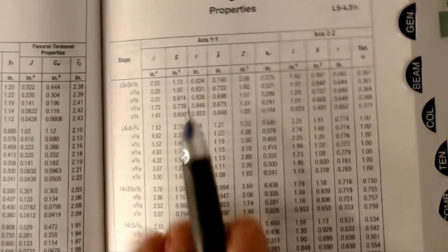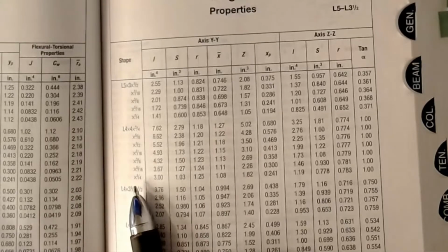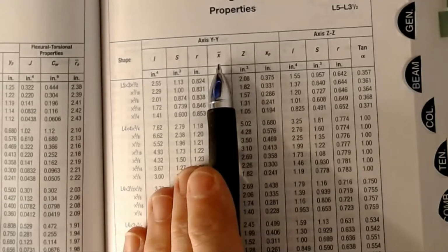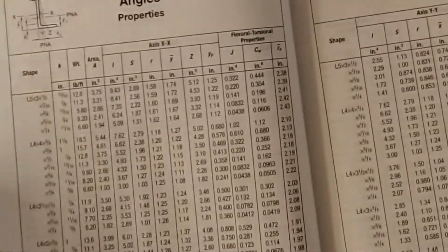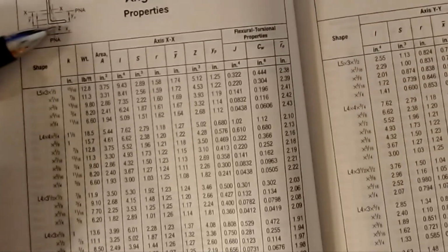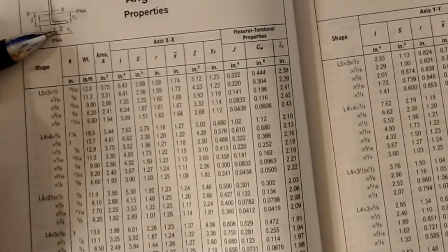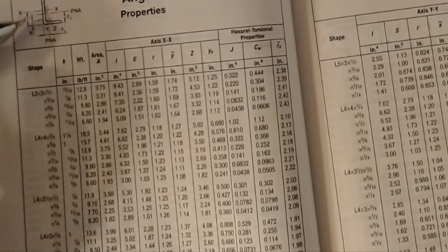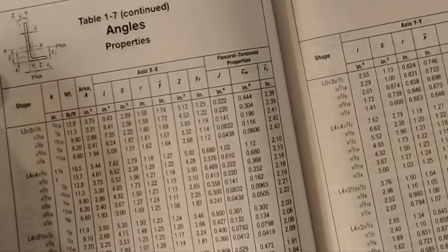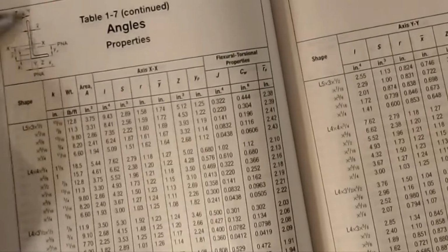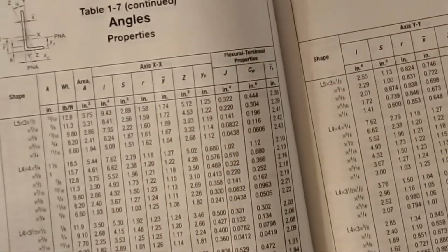Okay, now if we slide over, now we get into a y-axis calculation. And so 4 by 4 by quarter, and we come across and we have the exact same information, but now about that vertical centroidal axis. Notice that there's an x bar. Okay, and if we look back at the picture, our x bar dimension is going to be labeled from the left edge, if the angle were oriented this way, to the vertical centroidal axis. Now the thing that you have to be careful of in all of this is the orientation of the angle. If this angle were oriented such that the short leg was coming out to the left, then you would have to flip and transpose all of these dimensions appropriately. Everything is measured relative to the back of the leg. Okay, so that's one little trick that you've got to be careful of.